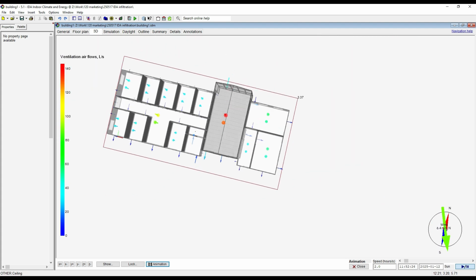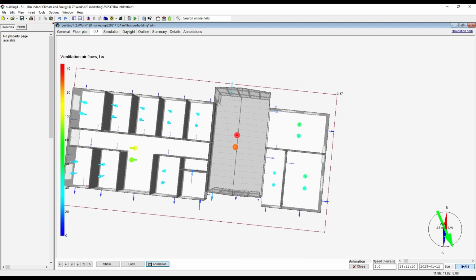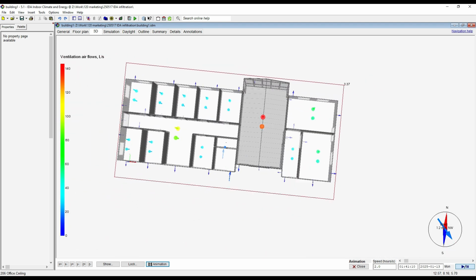But our zones are pretty much persistently in exfiltration rather than infiltration. I'm sure if we checked the graphs for any of these individual zones, with the exception of this outer plenum type zone, we would see that we're pretty much permanently in exfiltration in this building now because of the 10% oversupply. Like I said, this is a fairly trivial and ubiquitous situation in many buildings, but it's actually quite hard to model in most tools apart from IES.